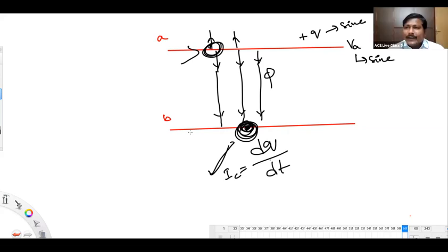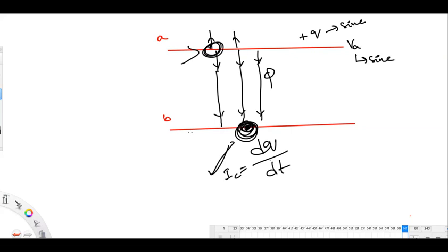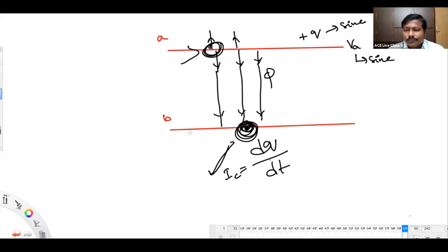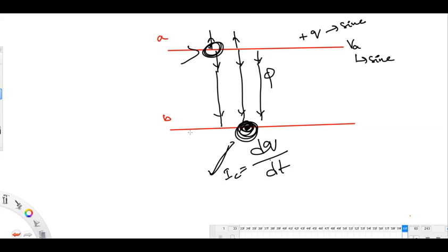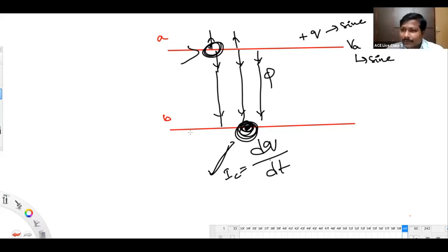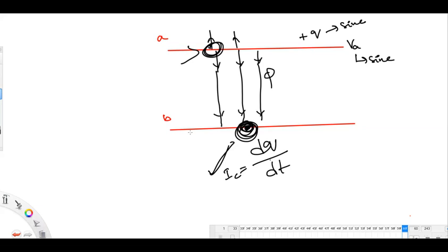The actual value we have taken is mod VS minus mod VR approximately, the base value is mod VR, and dividing gives the per unit. Then why divide the voltage regulation again by the base? Voltage regulation already has no units, so dividing it by the base is meaningless, right? Okay, sir.